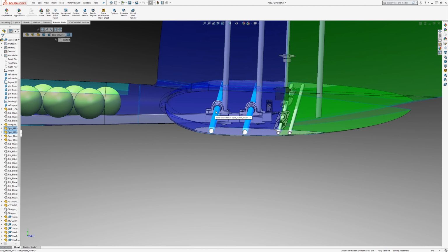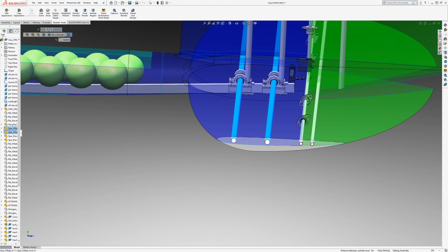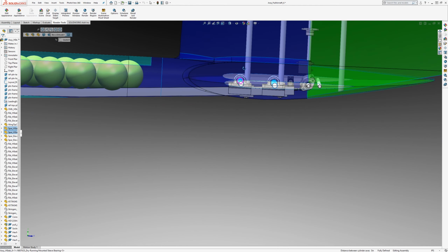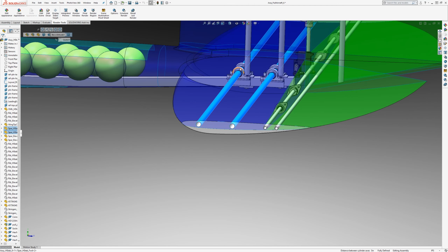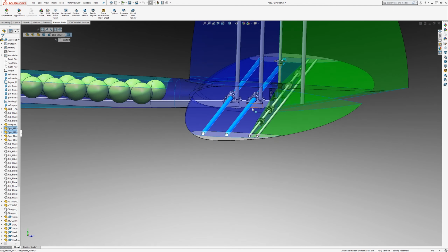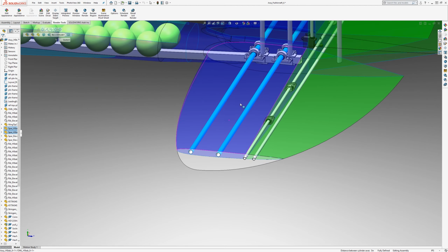So the resulting lift and torque in this case is entirely done by just two passages of shear, from one spar to the fuse and the other spar to the fuse. Each individual spar does not pass any moment, but the resulting two shears equate to the moment and force that the HStab is putting onto the fuselage.